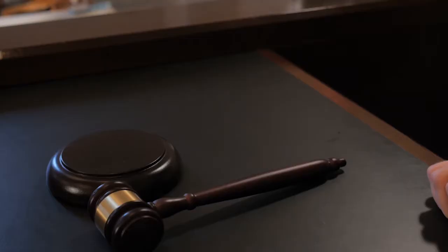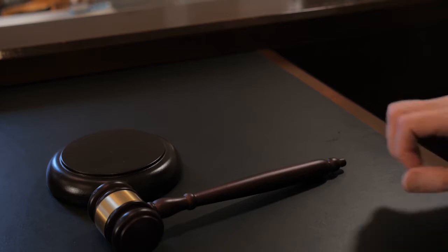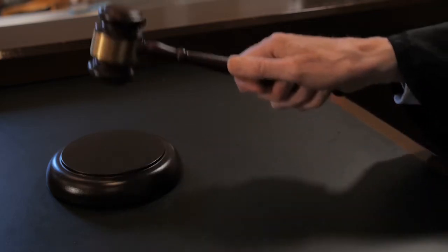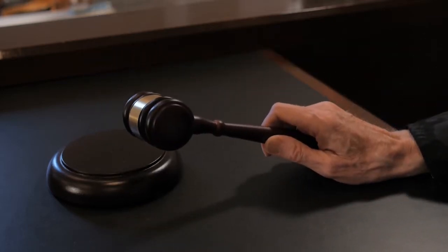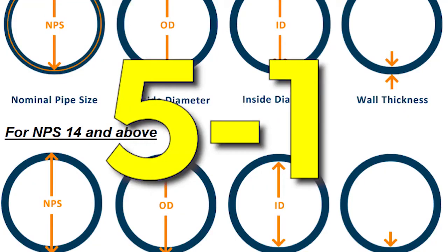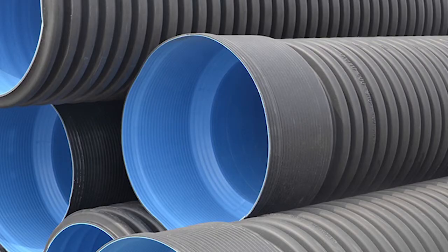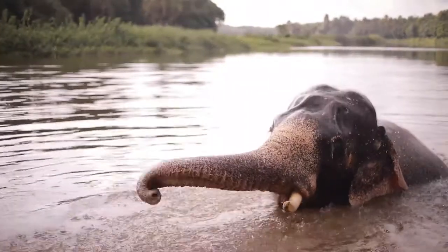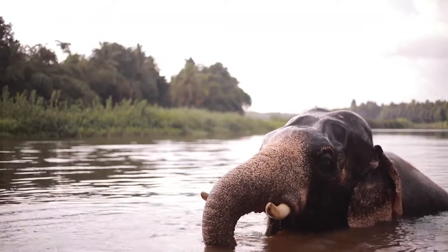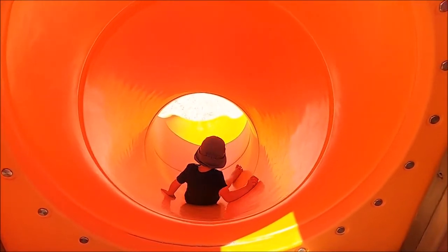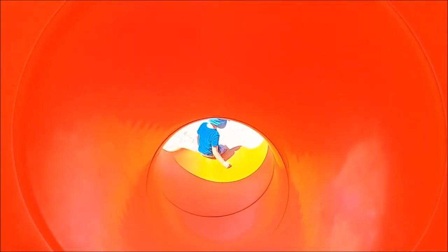However, the said disagreement was resolved as the Uniform Plumbing Code Committee formulated data as guide and references in determining the size of the waste and other drain pipes. The findings were enumerated as follows. 1. Waste pipe must be of sufficient diameter to afford adequate velocity of flow in order to make them as nearly self-scouring. However, increasing the size of the drainage pipe does not guarantee effective scouring action or self-cleaning ability of the pipe. Self-cleaning ability is present when the liquid and waste inside the pipe flow smoothly and simultaneously together.